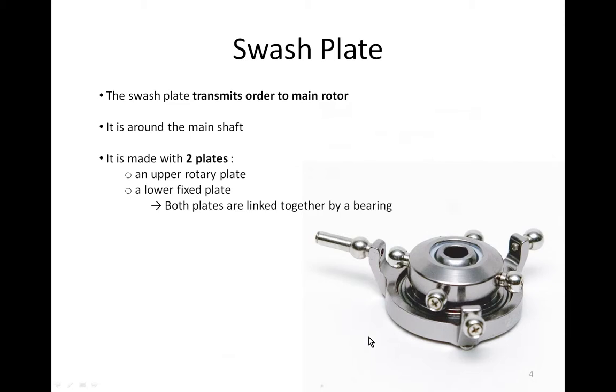Now we will see the swash plate. This is a component of the rotor. It transmits orders to the main rotor. Orders will be translated into pitch variations. It is located around the main shaft. The main shaft is here.